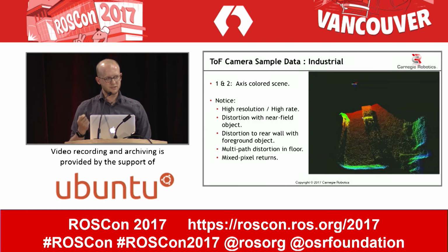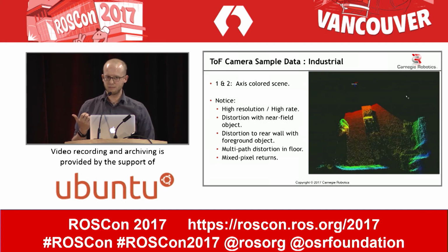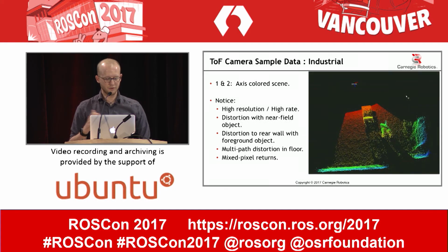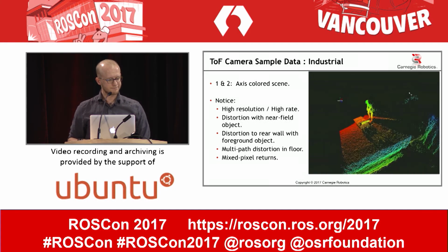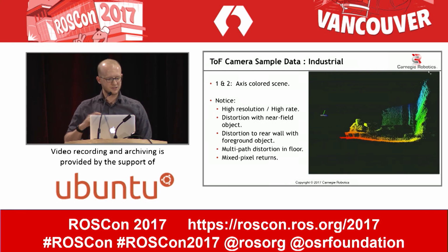You also see a bunch of data in between the person and the back wall that they're standing in front of, sort of the same mixed pixel return problem that LiDAR cameras have, or that 3D LiDARs have. And you also see some pretty severe bowing to the concrete floor caused by multipath.